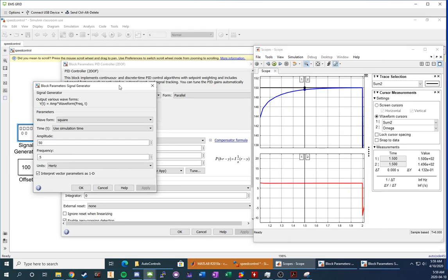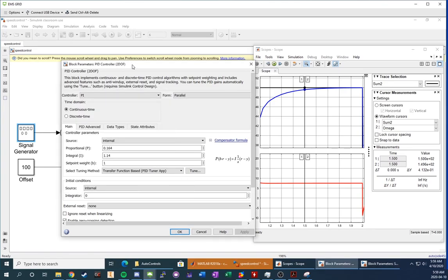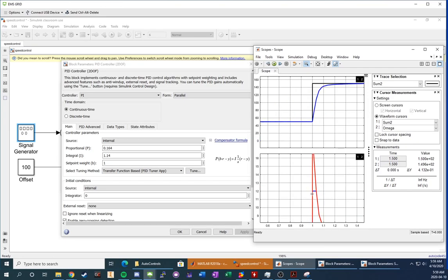The next step within the Ziegler-Nichols method is to adjust your gains around a little bit and see if you can create that slightly underdamped response while remaining unsaturated. What's unsaturated mean? Look at the lower response here. In this particular case, we are actually saturated.